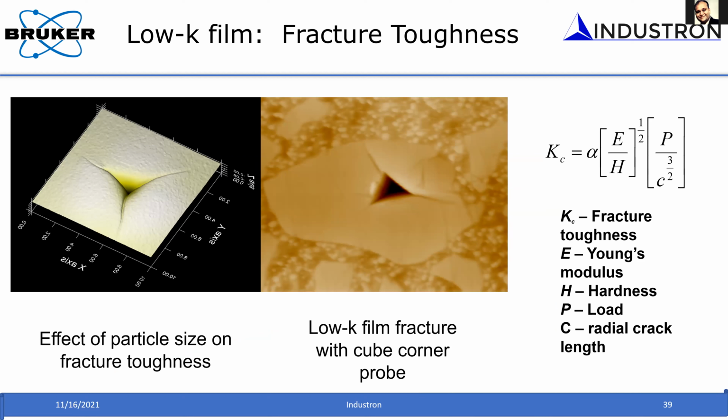Through SPM imaging you can measure this crack length, and through indentation you can measure both hardness and modulus, and with the known crack length you can also measure the fracture toughness of this material. So with in-situ SPM imaging, that is the key, you can do all of these things very nicely in the same setup. Okay, so not only measure the hardness and modulus, you can also use this similar transducer technique with in-situ SPM imaging.